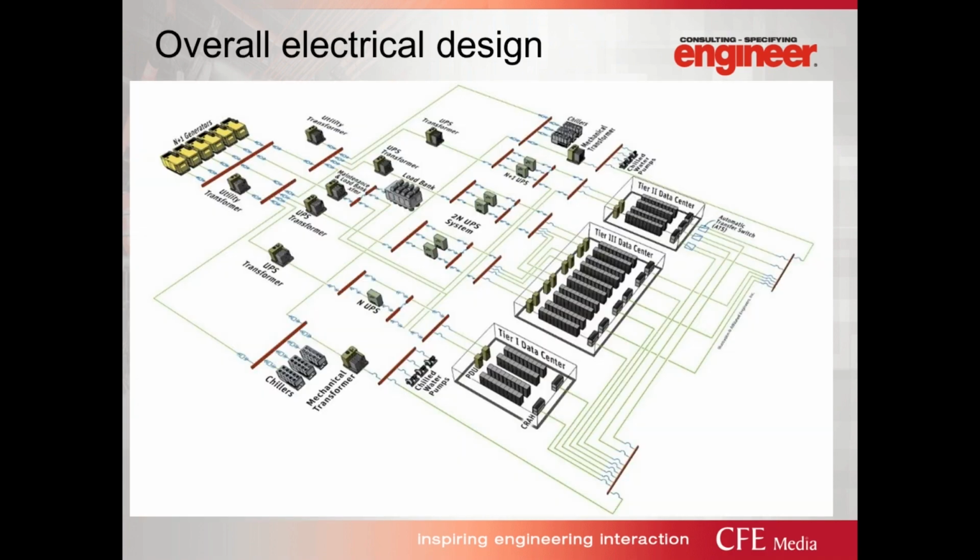So for the overall electrical design, we need to start with the end in mind. Oftentimes we'll design with our final build and then peel backwards based on what's needed day one versus the owner's budget. Because one thing where people can run into trouble is if they haven't planned properly for scale. Let's say that you have a paralleled common bus for generators and you'll want to be able to scale that up.